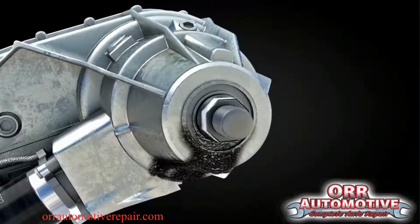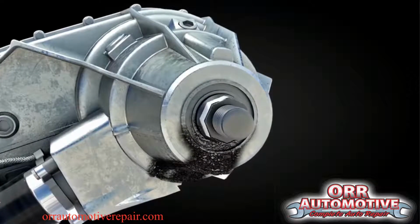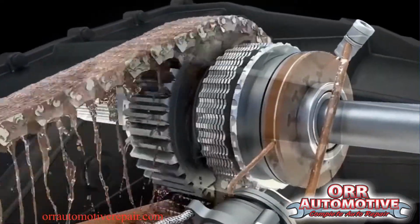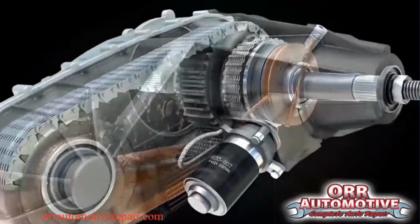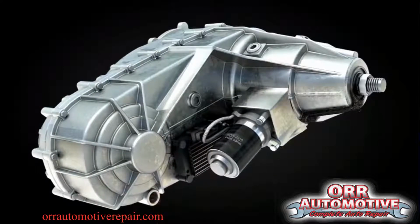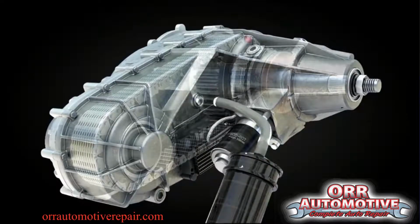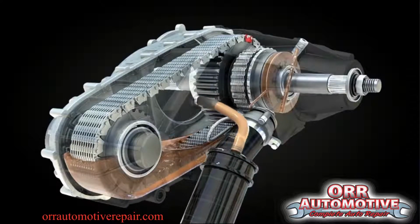Damaged or worn transfer case seals can allow fluid to leak. Running the transfer case with low fluid can cause internal damage to gears and clutches, potentially causing the transfer case to fail. Leaks should be repaired when discovered, and the fluid should be replaced to remove any internal debris.